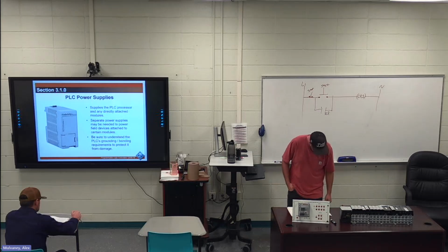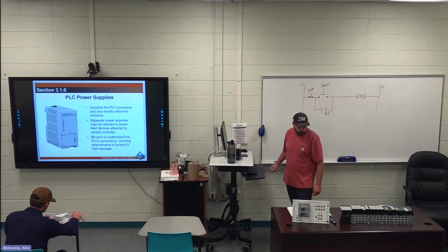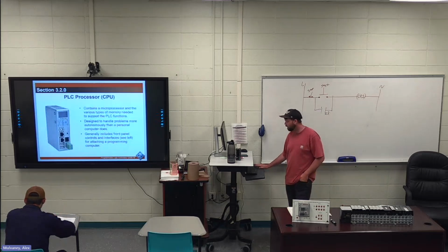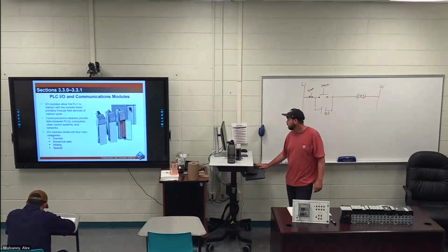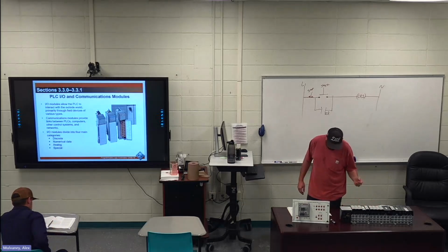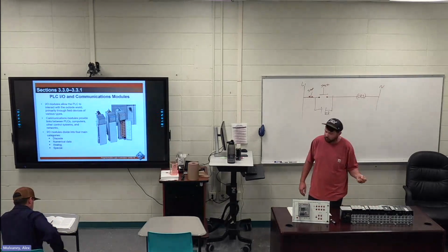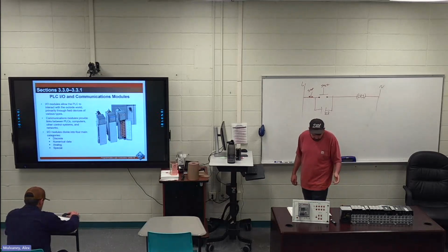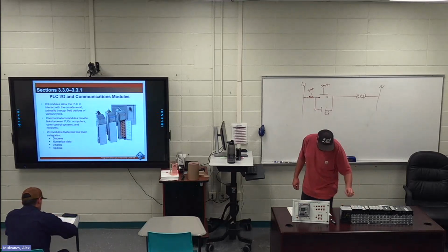And page 16, IO and communication modules. I've talked about IO modules quite a bit, the different modules inside of this. So you can have discrete, numerical data, analog. Special would be like an RTD or a thermocouple specific module.